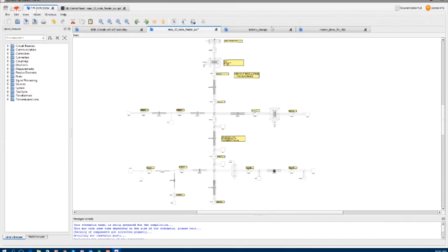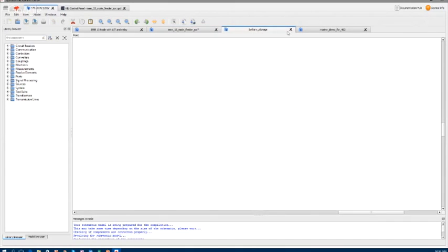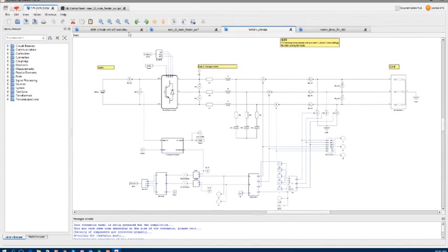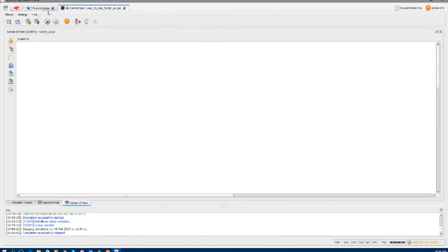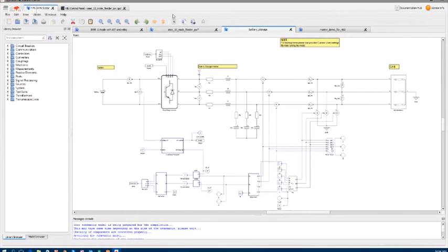Now, as a next step, I would also like to quickly show you how this looks on some different examples. For example, a battery storage inverter working in the grid connected mode. In this example, we are going to run the converter with the control that we also designed in our system. Then we are going to start injecting some harmonics and different grid faults into the system, stop the simulation, and play with this circuit for a while so that you can see what kind of tests can be performed easily.